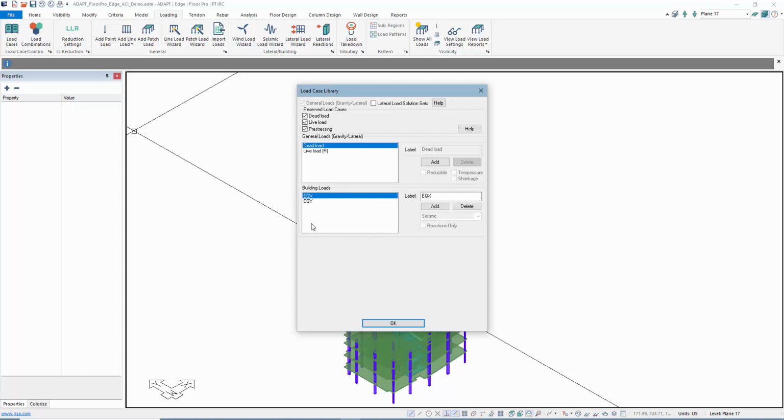going to be stored here, and any load combination that includes wind or seismic in this case would be required to be solved using multi-level mode if we want a solution for those particular load cases that are included in combinations. Gravity loads, self-weight, dead, live, and those types of loads that are classified as general loads will always be solved regardless of the mode that you're working in.